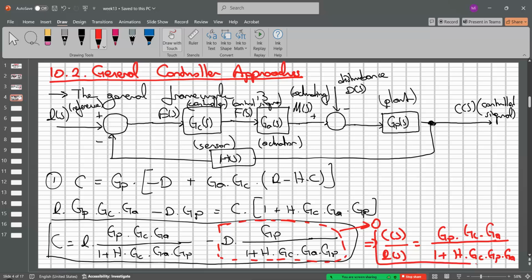This is our basic transfer function for closed-loop system analysis, because we don't have any model of the disturbance value. But if you have a model of the disturbance value, you can use the general form. Generally, we use this kind of condition. After that, we should design our controller based on the characteristic equation, the denominator of this transfer function. Okay? Any questions?